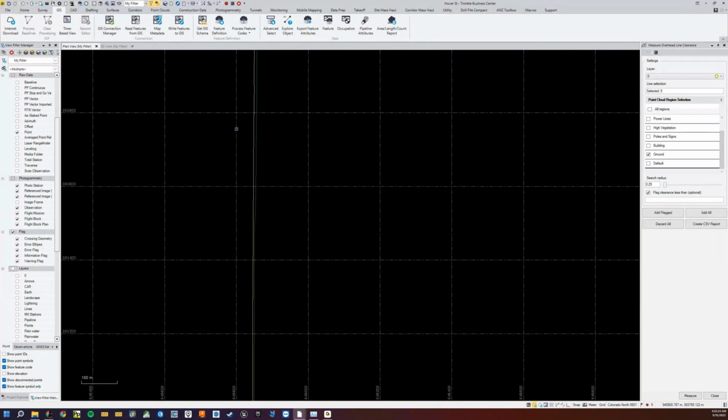So that's the most integrated option for ArcGIS. But the downside is you only have manual measurement tools available to you. The other option is to do your extraction in TBC and use the GIS Connection Manager to connect to a GIS Esri geodatabase that is then live between your ArcGIS Pro project and Trimble Business Center.